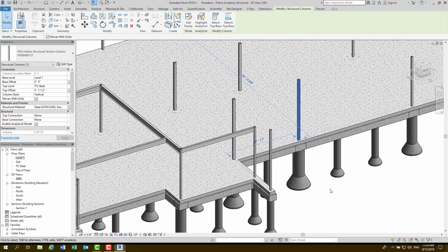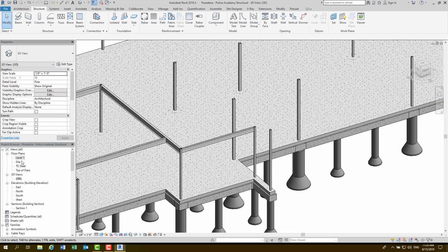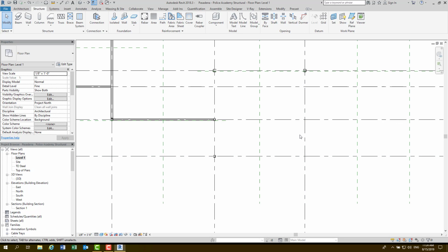All right. Now it does say there's supposed to be a column right here, but it doesn't tell me what size the column is. And not only that, it doesn't really locate it very well for me. So that's another one that I'm probably going to have to ask the project team to get with the architect and get some answers, because it doesn't even show the column. It just says what the top of steel is supposed to be. And I know that steel is not just going to be cantilevered, it's going to be sitting on something. So I'll have to ask on that one.